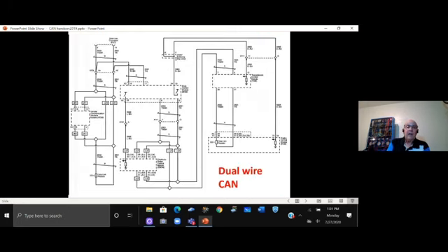Okay, if we take a look at a 2-wire CAN, there's a couple of things to recognize about it. The first thing is, it will have 2 data link resistors, which may or may not show on the wiring diagram. Now, if you're going to use a wiring diagram to teach from, don't use Fords, because most of the Ford wiring diagrams do not show the data link resistors because they have them in the modules. This one shows in the lower left-hand corner that 120 ohm resistor is sitting out somewhere. Do we know where? Well, no, we'd have to use a component locator.